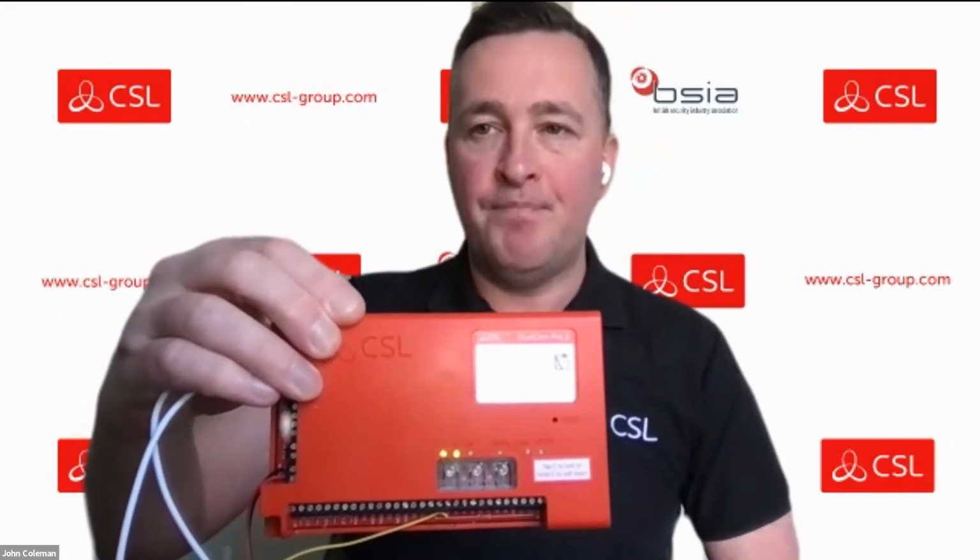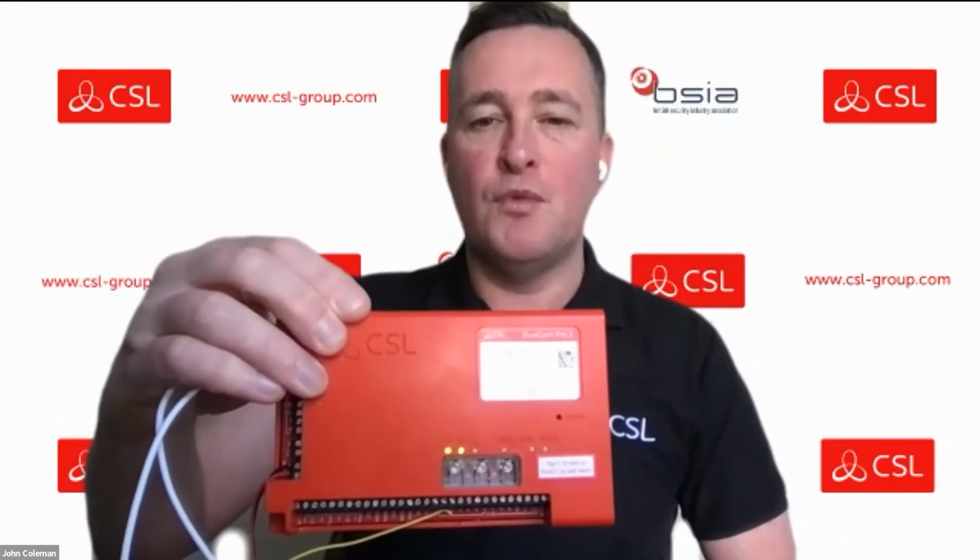If it's on green, signal strength is above 40% for both of the modules. If it's on green flashing, signal strength is between 30 and 40%. And if it's red, it means that your signal strength isn't acceptable, so you'd have to relocate the aerial. If this was a DigiAir that I'd installed, then I'd only see one of those LEDs on there.